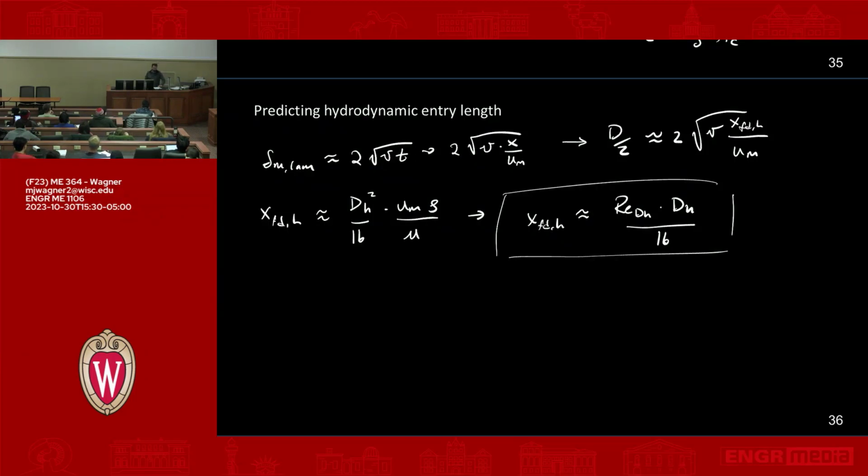One last thing I want to say is we've defined things in terms of this Reynolds critical. If it's in terms of x, normally that's about 5e to the fifth. If we're now defining it in terms of the hydraulic diameter d_H, so it's no longer a definition in terms of x, it's a different Reynolds critical.